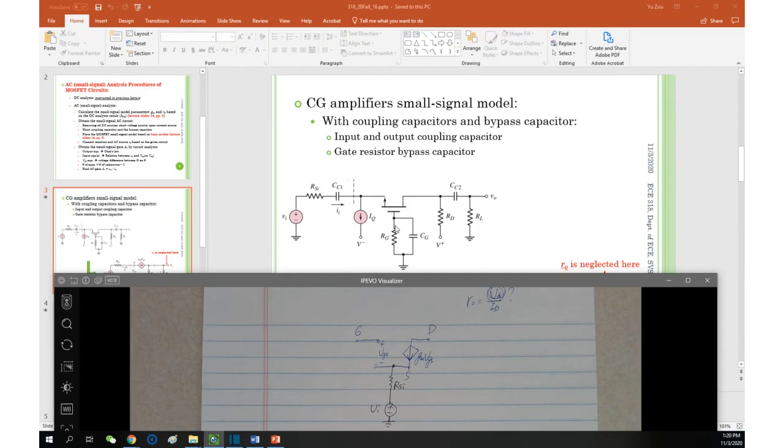Makes sense. Next, let's take care of the drain. The drain is the other side, the output side. CC2 is shorted, so the drain connects to RD and RL. What is the relationship between RD and RL? Parallel, very clearly parallel, between the ground down here and the drain up here.